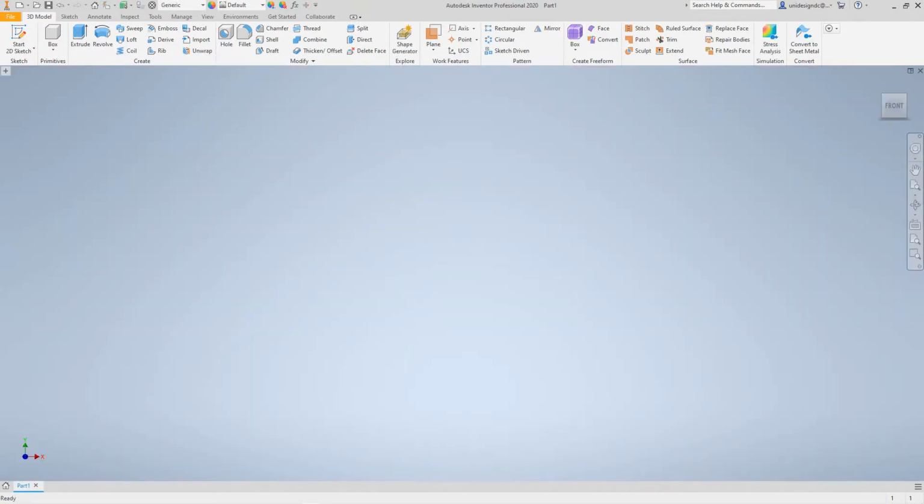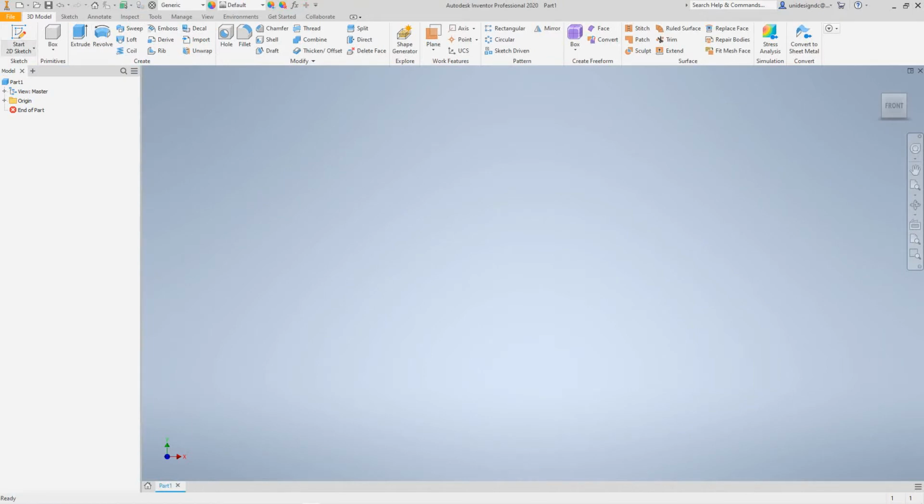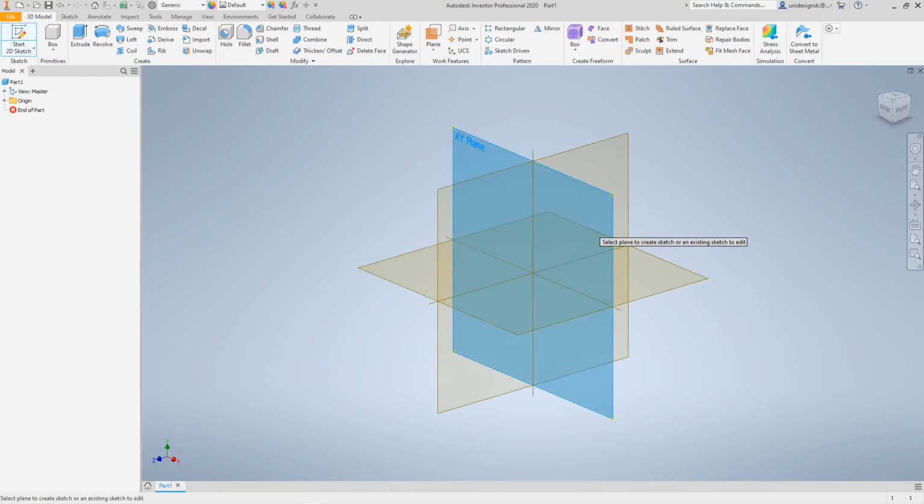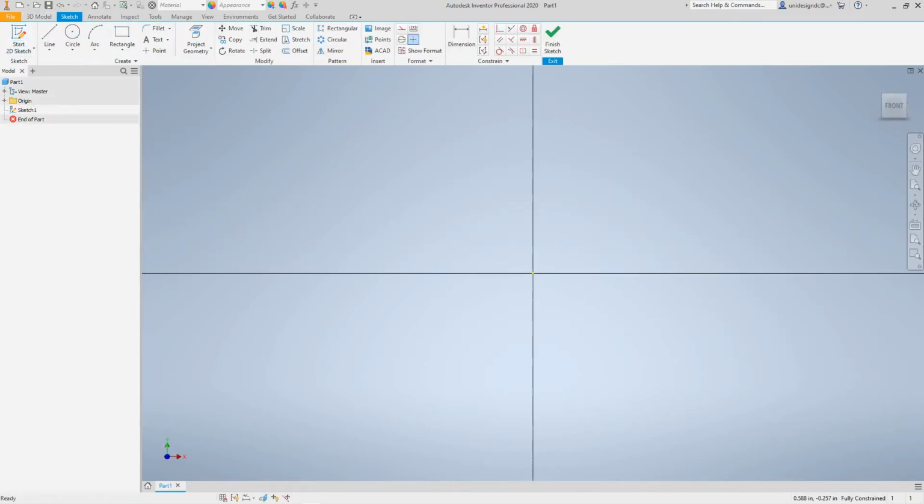So now we finally got it open, and let's go and do our 2D sketch. And we'll click our XY plane. So once we get our XY plane, we want to click circle center point. And we'll draw a circle right about here. If you're following along, it doesn't matter the diameter here.